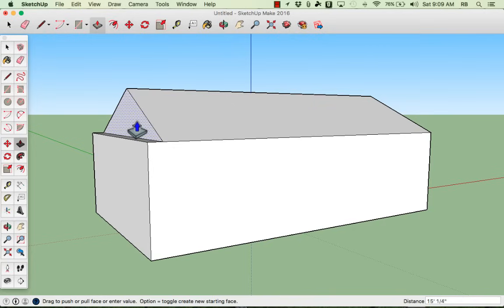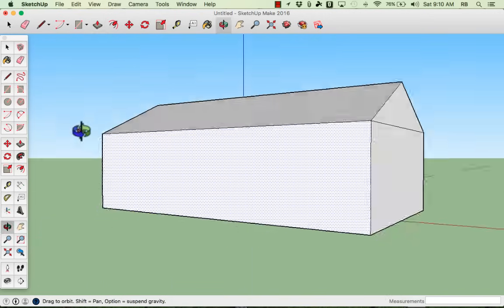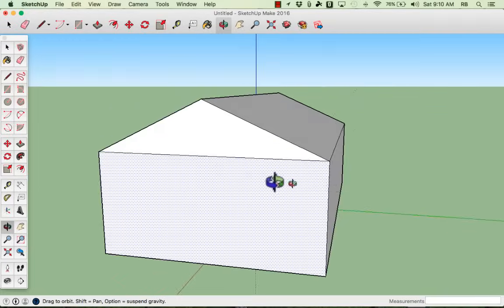So just to give you a little trick that you can use, it's really easy to make this line up perfectly with the house down here. All you need to do is, while you're using the push-pull tool, you still have your finger clicking the mouse and holding it. Just click and drag and pull down, and notice what happens. You see that dashed vertical line? That is indicating to SketchUp that I want this surface here to match up exactly with this surface down here. All right? And then you just let go. All right, our house is coming together quite well at this point.